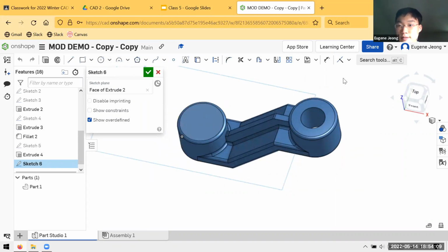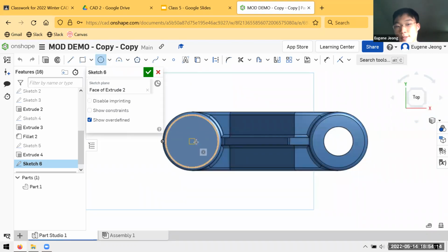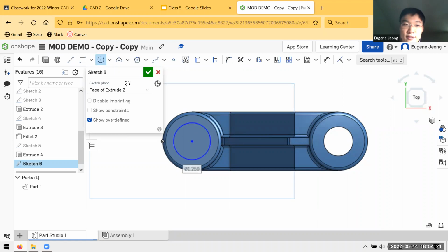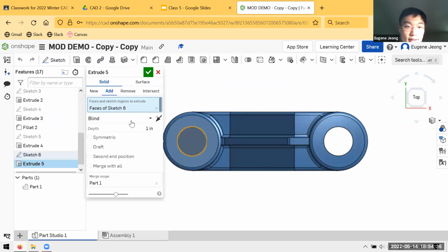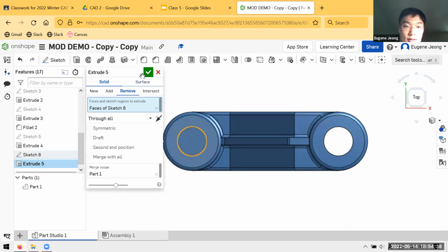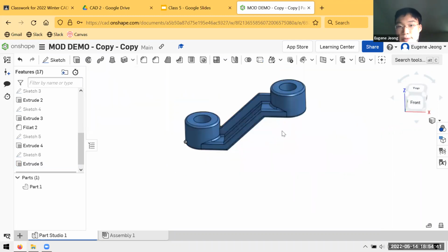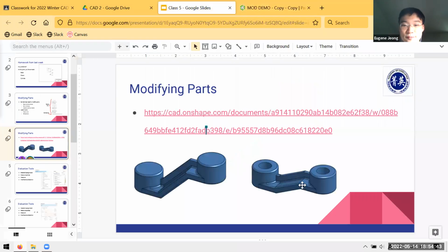You'll notice when I try to make these sketch circles, for example, Onshape gives me a lot of help here. If I click on this highlighted box that appears in the center, it'll automatically be located for me. You can see the center turns black as soon as I click it. That just means all the necessary relations have been created to fully define that particular point. So that's the first part, or the second part, whichever.